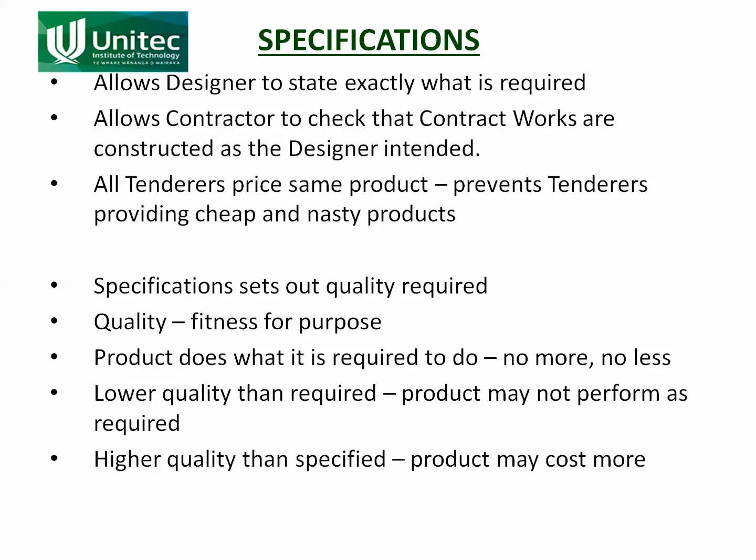So what you do is the designer says, this is what I want, these are the things that are of the appropriate standard, and all tenderers have to price that. It stops tenderers from providing cheap and nasty products which won't do the job but save the tenderer money. So they set out the quality required, and you recall that quality is fitness for purpose. It does what it's supposed to do, no more, no less.